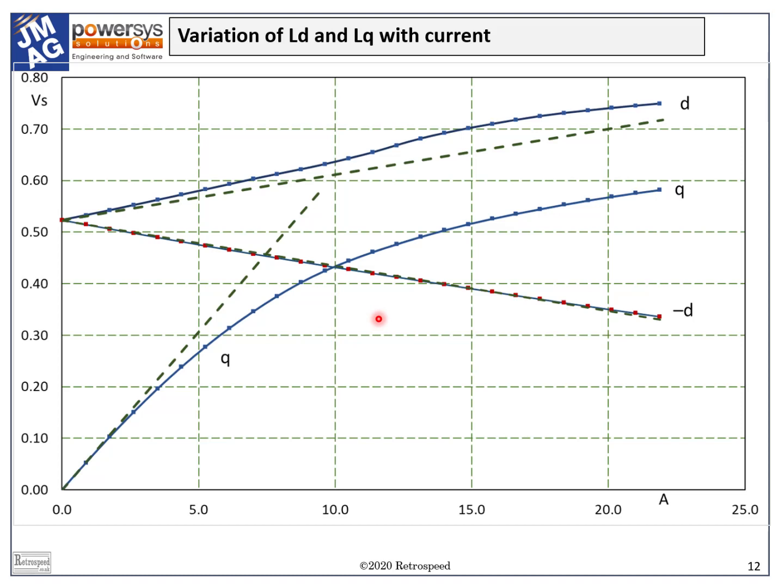In fact, we will have a closed-loop control which generates a current demand signal, just as we saw in the induction motor controller earlier. But we also need to know that the inverter has enough voltage available to drive this current. So that is why the voltage calculation is important.